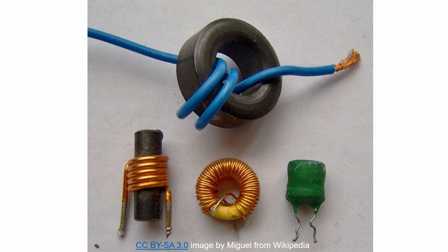An inductor is also called a choke because it tends to choke the flow of a fluctuating current through it. This property is used in the process of filtering a rectified direct current along with high value capacitors. As the inductance opposes changes in the current, it smooths out the ripples in a rectified DC.